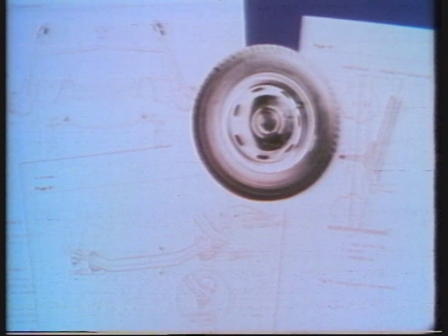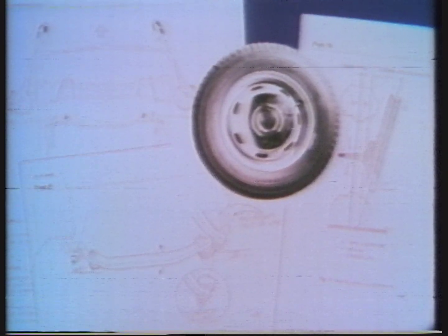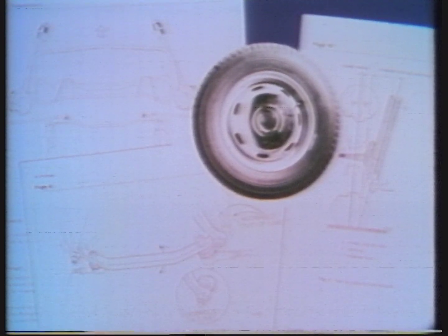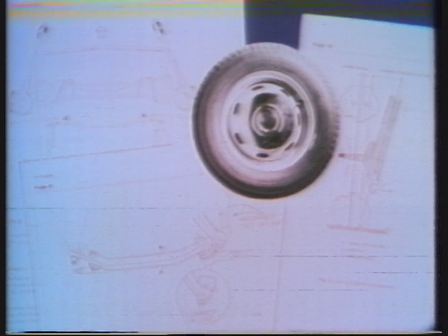Finally, correct hub adjustment and a check on all moving parts to see there is no undue wear, particularly at the ball joints and relay lever. Remember, the relay lever is allowed rather more vertical movement than some people expect. So refer to the workshop manual and bulletins to save yourself unnecessary work, which adds to the cost.